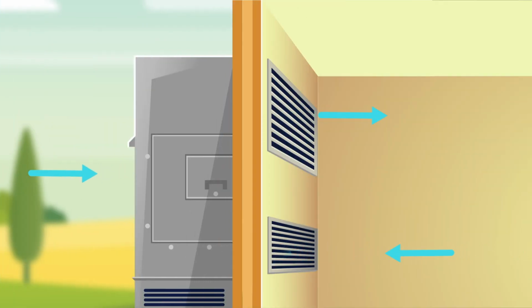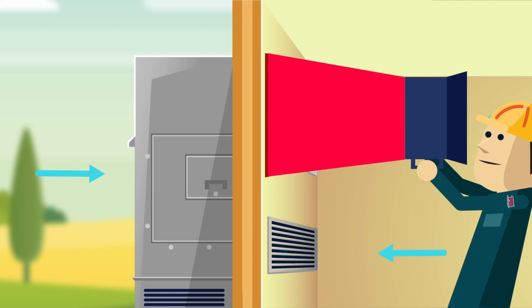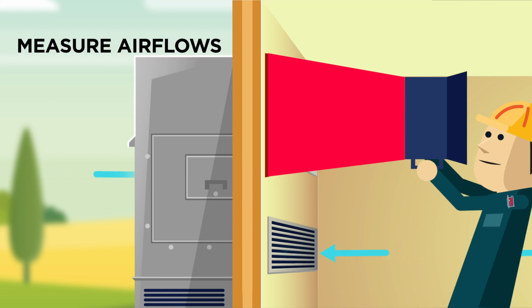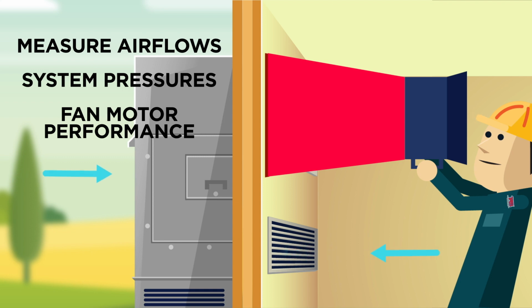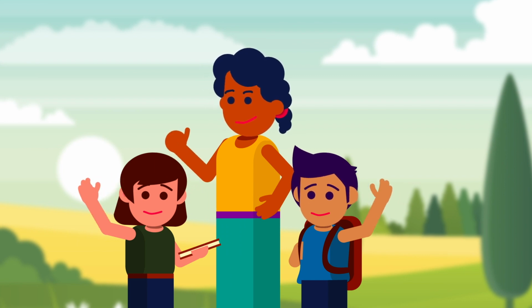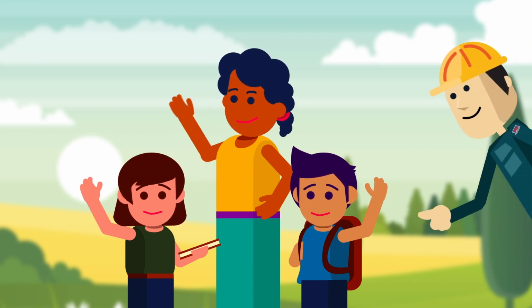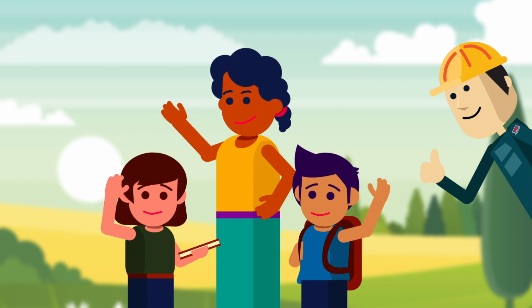Ensure that your MERV 13 filters are compatible with your HVAC system by using a skilled, trained, and certified technician to measure airflows, system pressures, and fan motor performance, and confirm they meet your system design. Ensuring adequate filtration and ventilation in classrooms is essential and will help support the health and productivity of students and teachers.